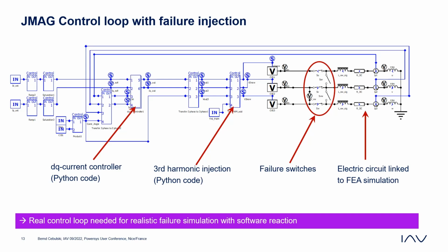The failure situation that your functional safety guy will tell you is normally not the one that is most probable. The most probable one is the one phase open. So just disconnection of one phase due to mechanical things or connector problems, but also a short circuit in the inner windings. So directly in the slot, for instance, from turn to turn, or just several turns crossed, which lead to overheating because you have a short circuit indirectly in the tooth. This can be quite complicated, but this really happens. So you have to know what's going on before you build the machine.